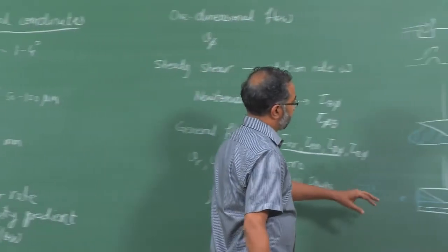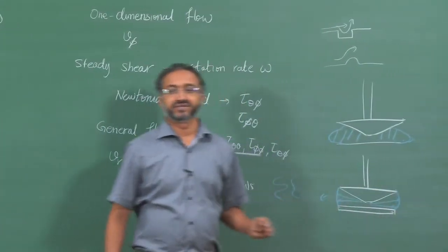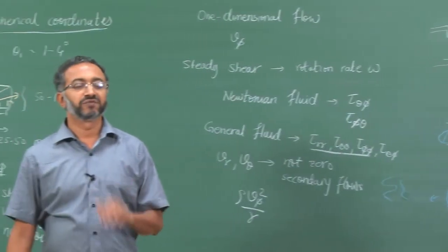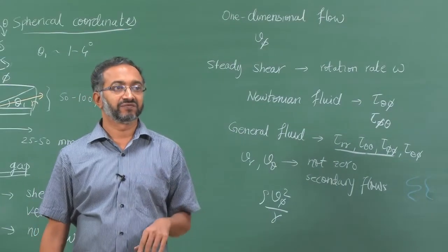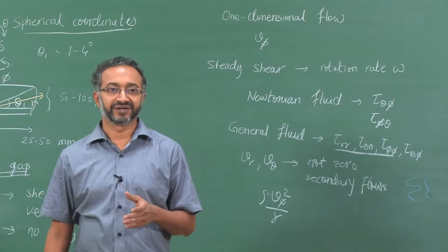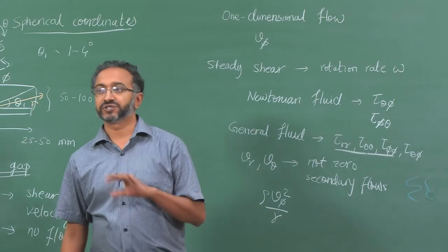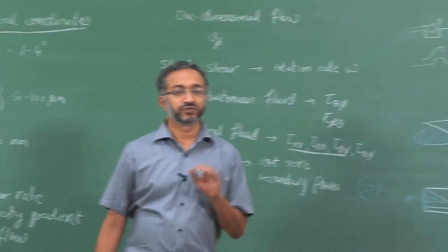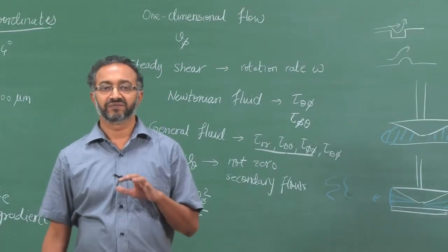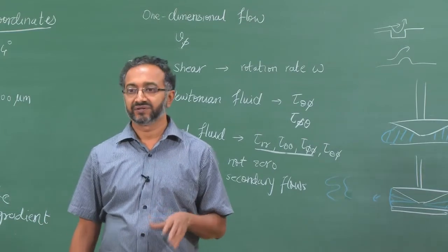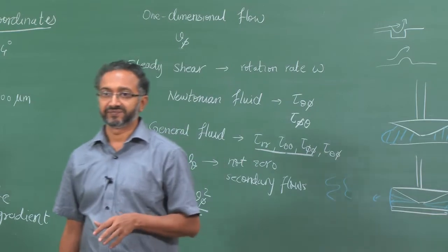And generally when we are working with low viscosity fluids, we would expect some of these effects to be more, because low viscosity implies inertial forces to be more significant. So, generally when we are trying to measure low viscosity materials, we should be very careful in terms of whether there are artifacts due to the secondary flows in the material.